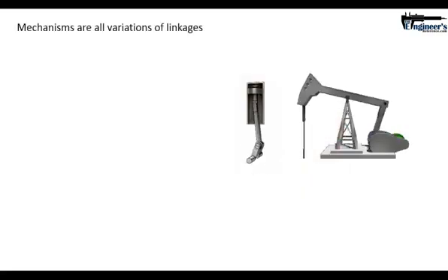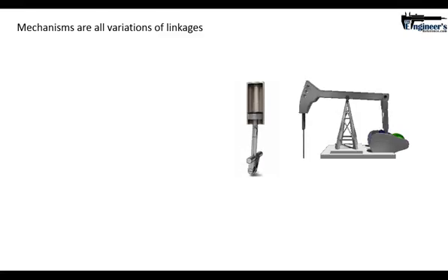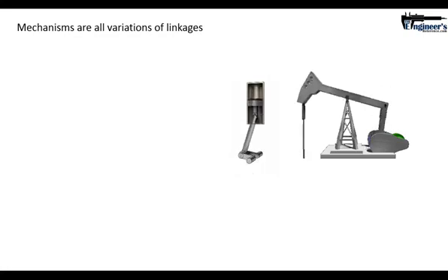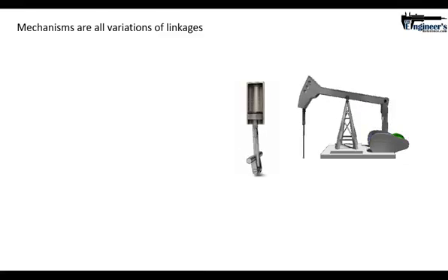Now, one way you can think of that robotic gripper is just a series of linkages. We saw it had a gripper that actually picked up whatever you're going to handle, and then there were a couple of rigid bars pinned to it, with joints that went back to a gearing mechanism. As the gearings rotated, it created an output that we wanted, which was an actual gripping action. That is the basis of most mechanisms. They're just a variation of linkages.